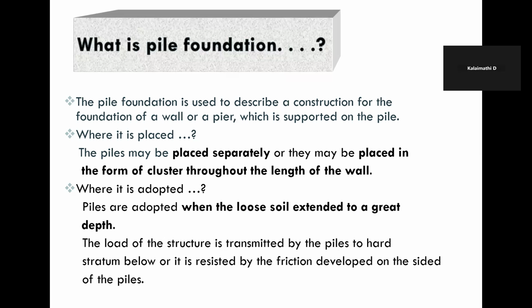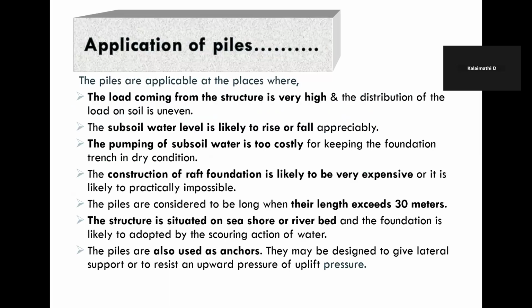And where is it adopted? It is adopted when loose soil extends to a great depth and the load of the structure is transmitted by the piles to the hard stratum below, or it is resisted by the friction developed on the sides of the piles. Piles are applicable at places where the load coming from the structure is very high and the distribution of the load on the soil is uneven. The subsoil water level is likely to rise or fall appreciably, and the pumping of the subsoil water is too costly. At that time, we can go for this pile foundation, where the foundation will be in dry condition.